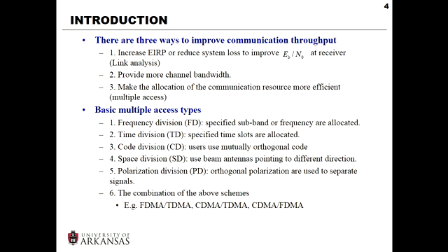Okay, just like what we did at our link analysis. So to increase power, that will sacrifice our energy efficiency. And also, actually, if the users share the same spectrum resource, increasing power will also increase interference to other users, which is not a good idea. You can increase power, somebody else can increase their power as well. And the end result is your signal to noise ratio is going to be about the same, right? You increase your power by 10 times, and the other user also increases their power by 10 times, and your interference in this case is going to kick in.